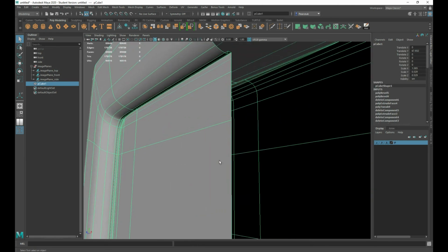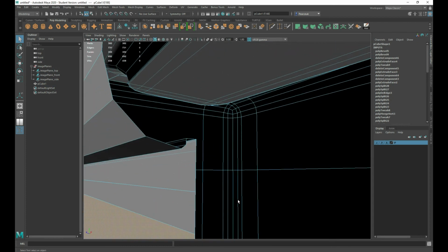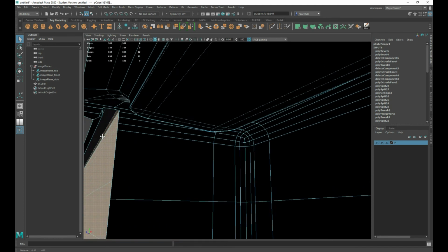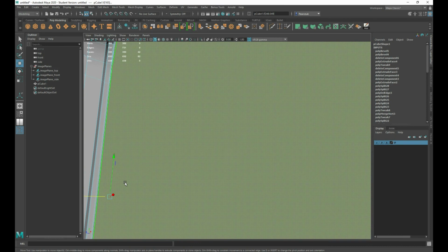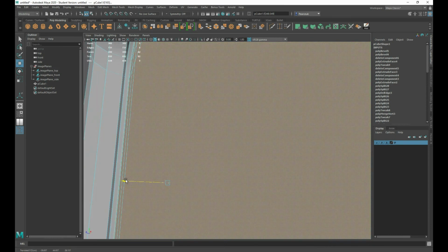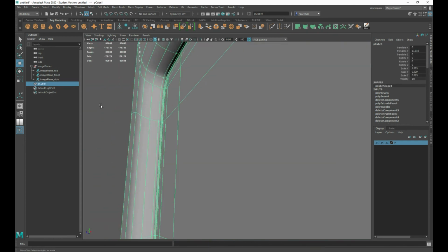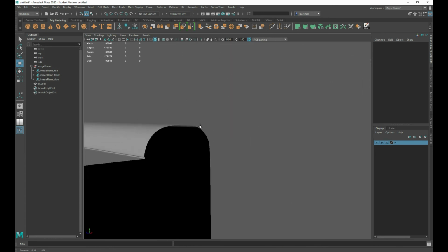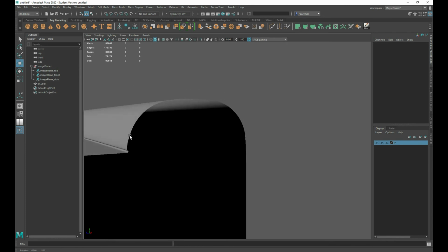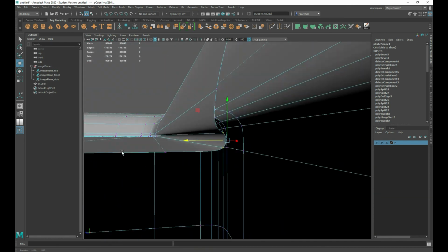It's relatively straightforward. I can select that and use the grow selection again. This time I want to make sure that I come in and select that edge on the top as well, so that when I bring this closer, we're looking at over here, I'm bringing that edge with me. So it's still, so yeah, I think that's a little better. So we've got that edge in there. We've got this edge coming in here. And if I want to zoom in, I can go to my, say, vertex, just select those and hit F on the keyboard, which will take me right in, and then it centers around this point.